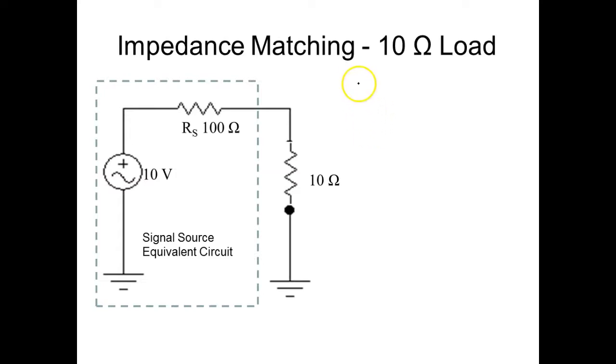So the voltage divider formula says the voltage drop across any resistor is equal to that resistor relative to the other resistors in the circuit, and that gives me the ratio that resistor would drop. That's at any voltage, and that's what's cool about the voltage divider formula. And this is the problem we have in DC. I say, okay, I've got a 10 ohm resistor in this series circuit, what's the voltage drop across the 10 ohm resistor? And you calculate all this. And I say, what would happen to the voltage drop if I change my input voltage to 20 volts instead of 10 volts?